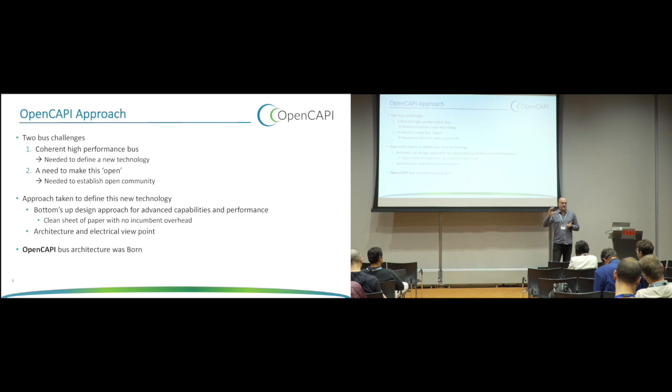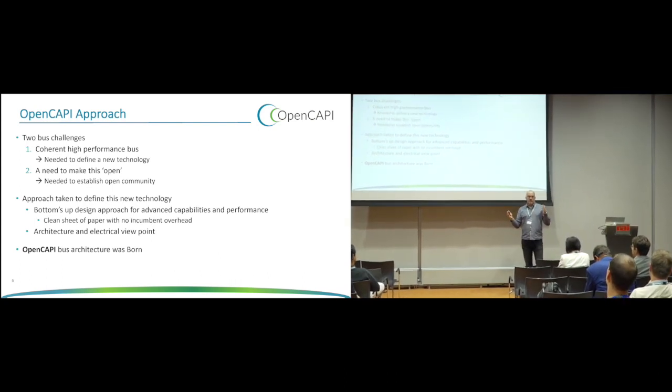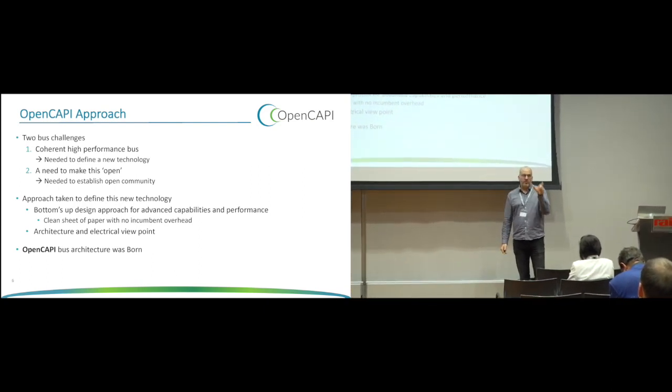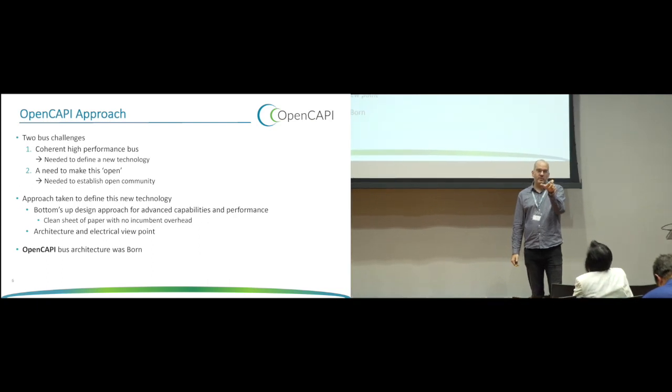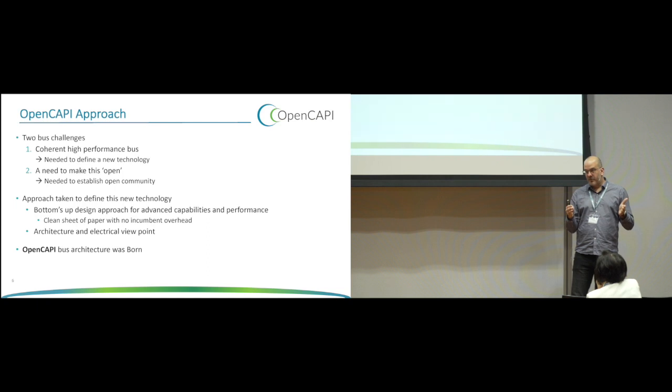So what we have is essentially a way to put logic on an accelerator or a memory and be able to get back and forth to the processor with very small, very specifically formatted packets. I don't talk about this in the session here, but the packets are strictly aligned to a specific cycle ratio in the processor. So when we send a 64-byte chunk of data between the processor and the device, we know that it will land on a specific clock boundary on the attached device. Because of that, we can start to interpret the data very quickly.